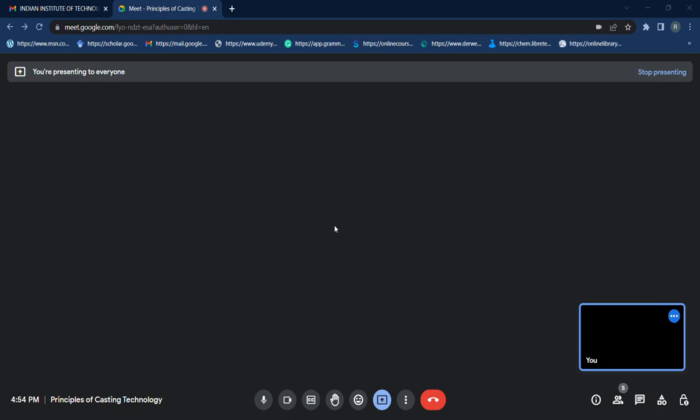So a riser can feed a maximum of 2T distance to the left and right part. This will be helpful in your problems if in the exam it comes up, till what distance your riser will be feeding. After that, you can see from this figure, the length greater than the maximum distance.